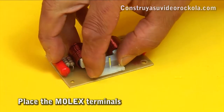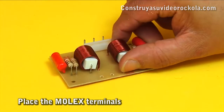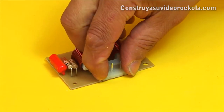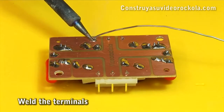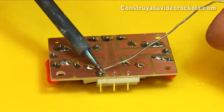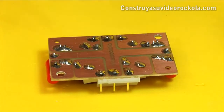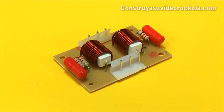Now, place the 6-pin Molex type terminals, to which we have previously removed the pin in between, and in the opposite direction, so that when installing the circuit, it can only be connected in one direction. Finally, we weld the terminals to the PCB. The welding should be plentiful, and perfectly surround each pin. We have ready our Zobel network, which we can use with a great variety of amplifiers. Success!